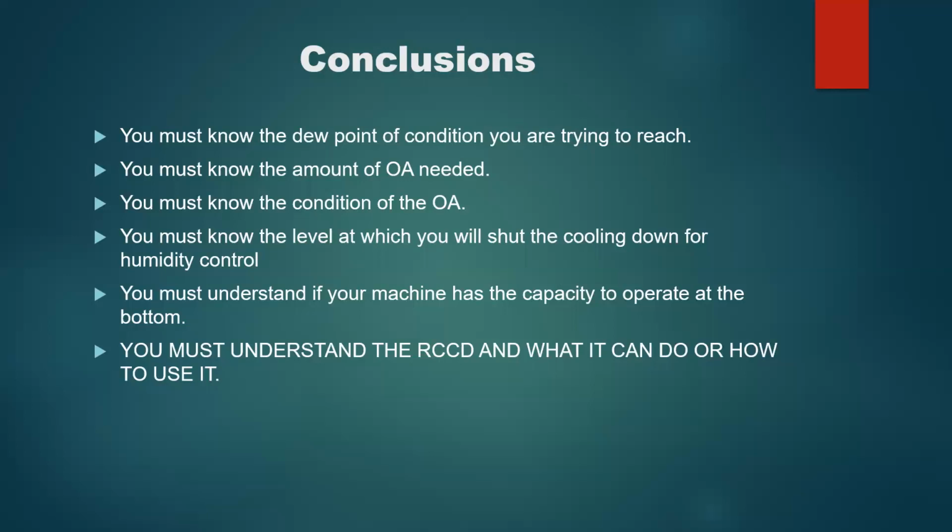A building will have a natural negative pressure, even with the stack effect, but you've got exhaust fans, who knows what all. And I've seen before on grocery stores where the people didn't like the makeup air coming in, so they would shut it off and somebody would forget about turning it back on because it was too cool. They did not heat condition the makeup air. And what I told them, I said, the makeup air was in a closed circuited hood. And I said, what you can do is put an outdoor stat on it, know what you're trying to do for conditions, and then you could shut that makeup air off at a certain temperature.